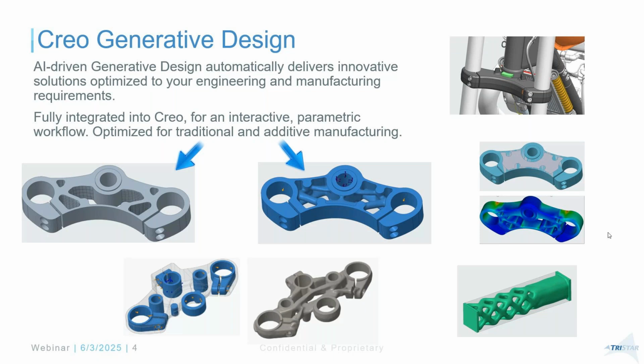So depending on your manufacturing constraints, the system is going to give you the geometry, which you could use as a starting point. You don't have to just use that, but that's a good starting point for engineers and designers. I've been there in the industry myself since 1996, where I've used various tools, and we are more used to the traditional optimization where you're telling the software, okay, I want the von Mises stress to be less than this, or my deflection should be less than a specific value, but here are my dimensions, here's my radius, here's my thickness, right?